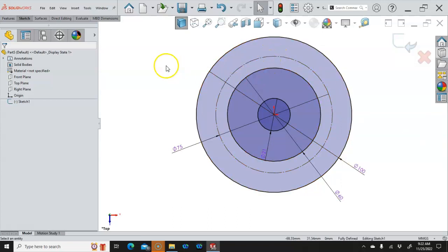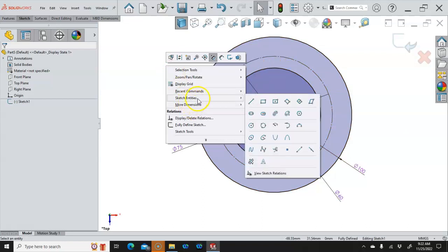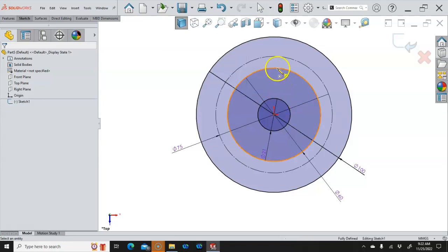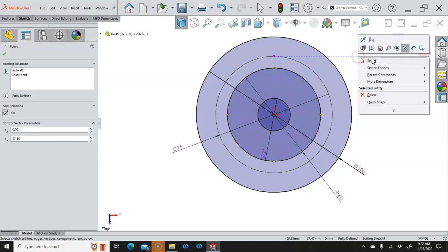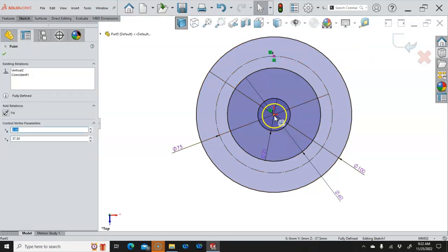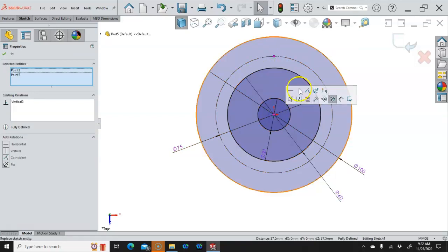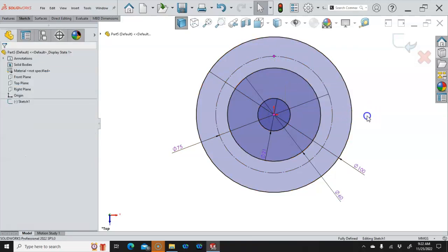And let's go the other route. I've been using the S key, so let's make sure that in the sketch entities you can also find the point, same as going up to the command manager and into the sketch. So place that. So pretty much I'm building all of the geometry that I really need into this one sketch, but I'm adding complexity, so I need to be able to manage this geometry. So sketch entities, and then we also have sketch tools, and we're going to, not seeing it, so we'll go back up to the sketch and circular sketch pattern.